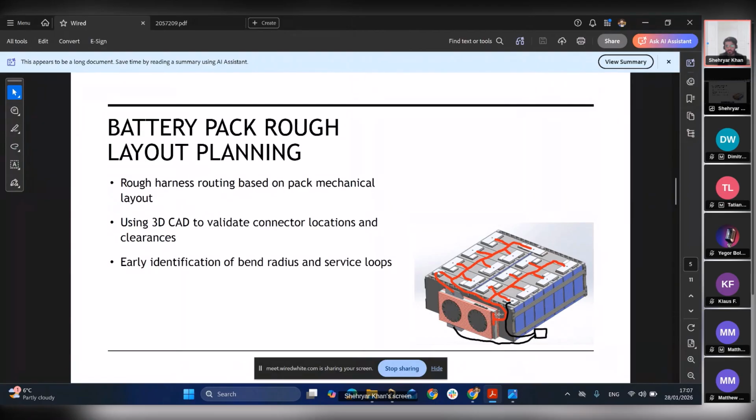The battery management control system controls the battery signals, and for that reason we have a connector which will be connected to all the ports in this battery pack. We have a JST XH connector for that, with 16 pins, where each pin will take the current to the batteries inside the battery pack.